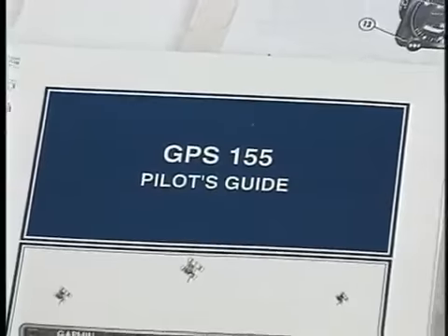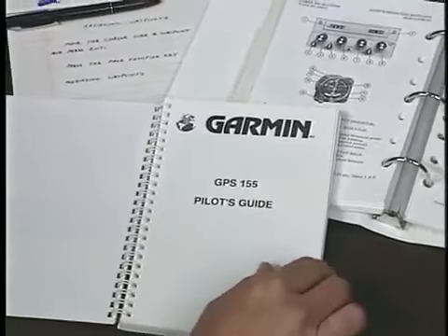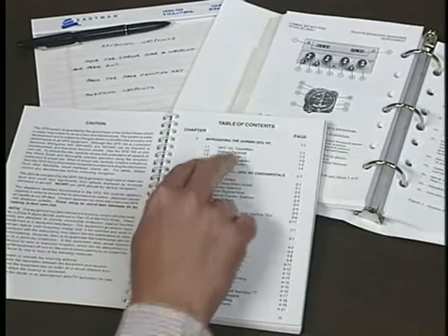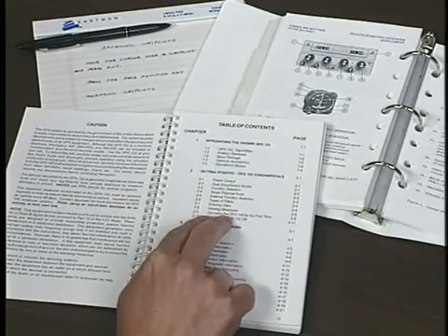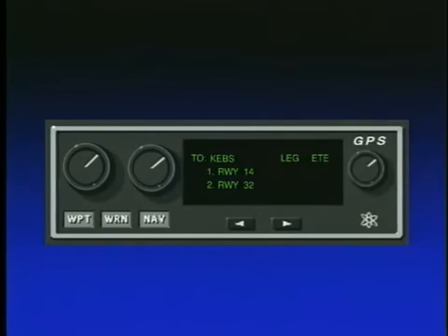Because there are a large number of GPS receivers available and each displays position and navigation information differently, you must be thoroughly familiar with the specific equipment installed in your aircraft, as well as its limitations. To fly a GPS approach, there must be a published procedure, and the approach must be retrievable from your GPS database. The database contains waypoints representing all fixes on the approach and displays these points in the same sequence as they are presented on the chart.